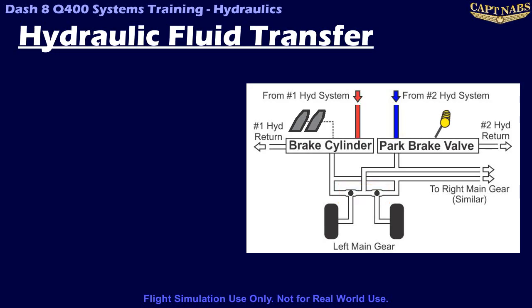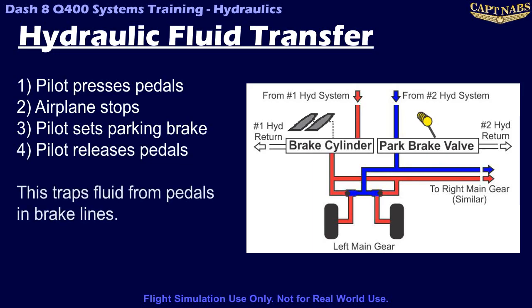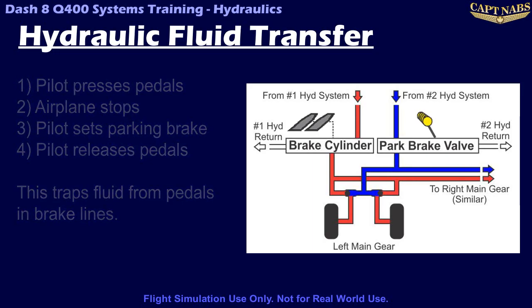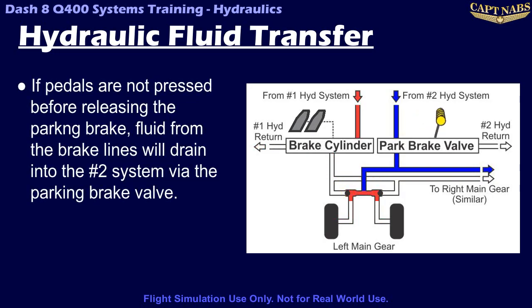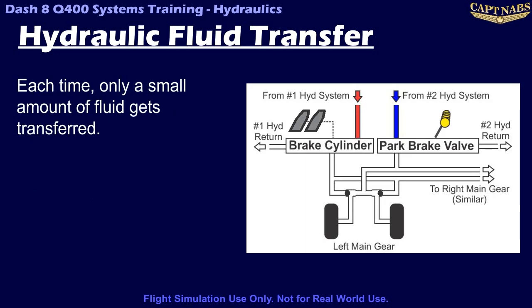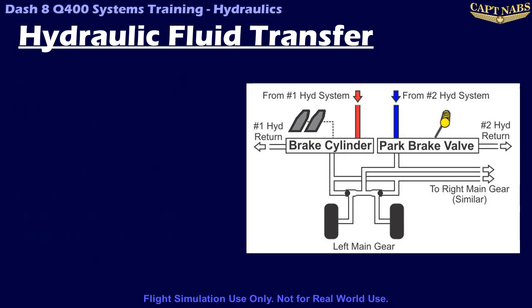The most common scenario you'll see in the Dash 8 is that pilots will press the rudder pedals, stop the aircraft, and then set the parking brake. Because the pedals were being held first, they forced fluid into the calipers. However, many Dash 8 pilots release the parking brake without holding the rudder pedals down. The fluid in the calipers then exits the calipers into the parking brake system. Each time, only a small amount of fluid is transferred, but if pilots do this a dozen times a day, after a few days, the number 2 system will eventually reach full and overflow, while the number 1 system has lost fluid and needs to be replenished.